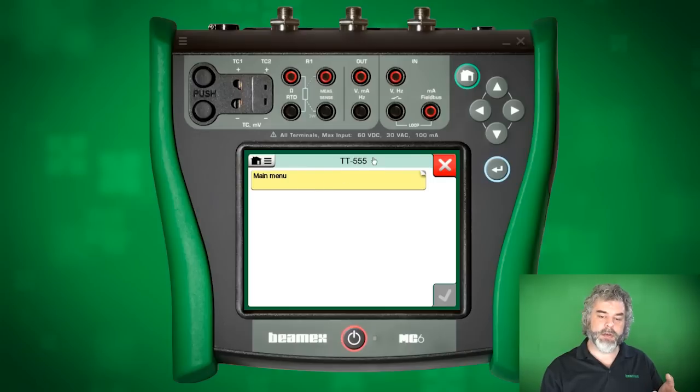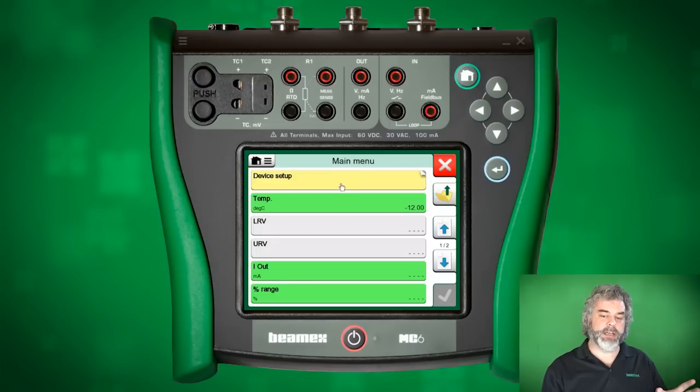Okay, main menu. Here's our tag on the top. I just clicked it. Now green represents a measurable variable. So we could also measure the digital HART output as well. You could display that if you didn't want to do the 4 to 20 milliamp output. You would calibrate using the digital representation, which would be here, the temp in degrees C. You would calibrate that if you were using that to control your DCS, your control system. But most tend to use the 4 to 20 milliamp to drive that control system, but you can do either.